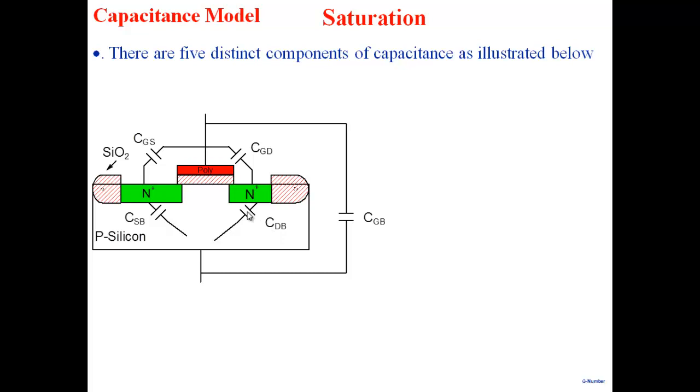The first capacitance that let's talk about is between the gate here and the source terminal, between gate and source. All right. Now, just keep in mind, what is the capacitance? If there is any charge in my system, and as I change the voltage and the charge changes, it will give rise to capacitance, right? Del Q by del V.